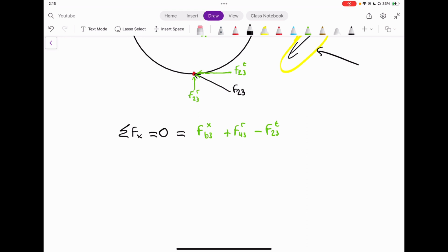Now, we know from our equations that Wt is equal to 60,000 times H over pi dn. Okay, we know that term, and that's a given. So based on this equation, we can then try and identify what Wt would be.